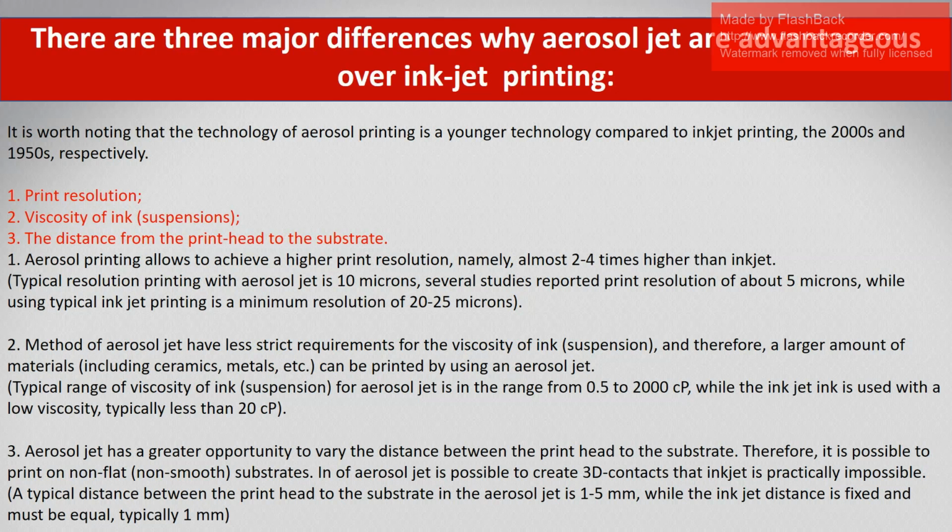The third factor is the distance from the print head to the substrate. The aerosol jet has a greater opportunity to vary the distance between the print head and the substrate. It is possible to print on a non-flat substrate and also to create 3D contacts, which is practically impossible with inkjet.